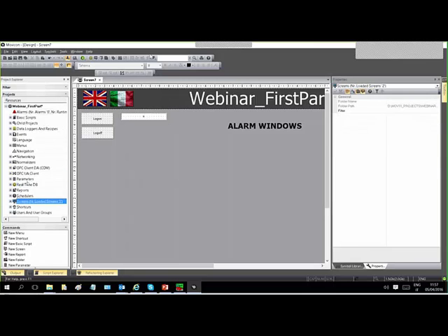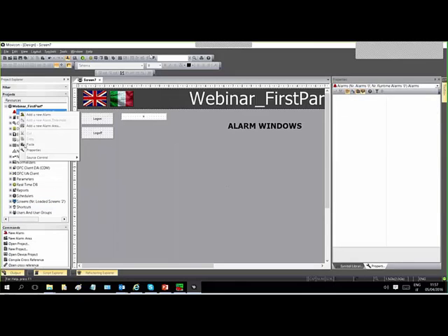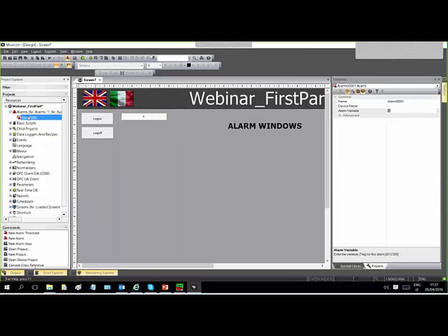How you can generate the alarms. Right click or command, add a new alarm. Looking at the alarm properties, we move as usual to the property window on the right: alarm name of the resource, device name. You can enter here the device name associated to this alarm, as additional info. You can associate which variable triggers this alarm event. It could be a bit, or an analog variable.